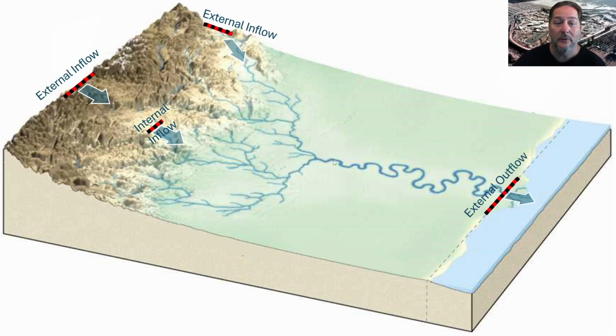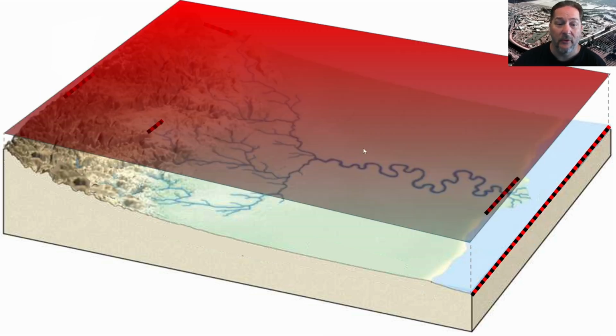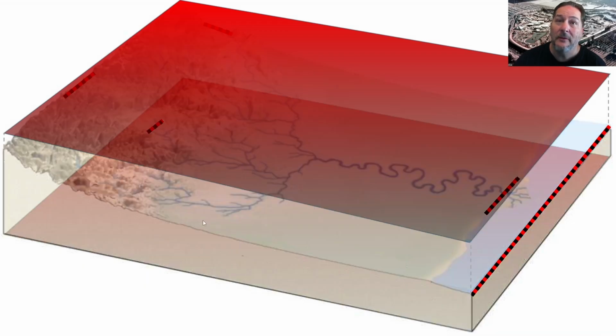The external outflow could be an energy gradient or a rating curve here along the edge. This location assumes that our perimeter stops right here along the dashed line. This can only bring flow out. But if we extended it all the way out to the coast and didn't have this one as the external boundary, then you could have an external stage boundary condition. And for this one, flow could go either way. We could also drop precipitation on it from the top, or even though we don't technically consider these boundary conditions in HEC-RAS's terminology, you can lose water through the bottom as well, even though the model just removes it from what's coming in from the sky.